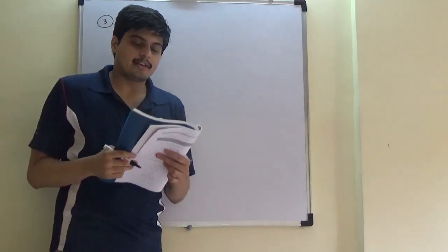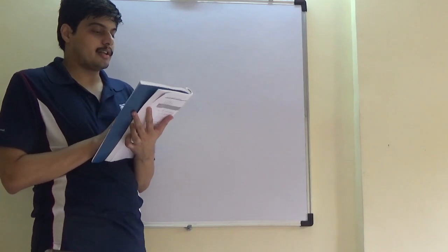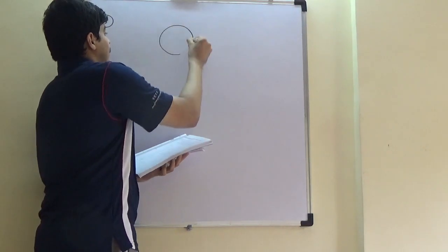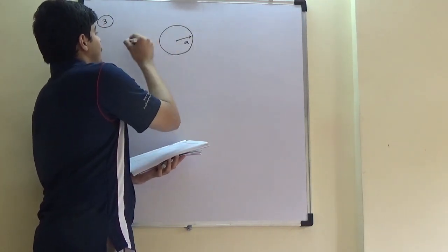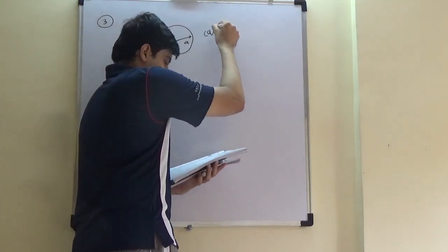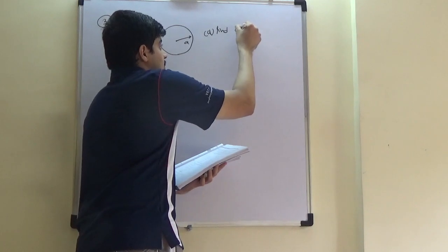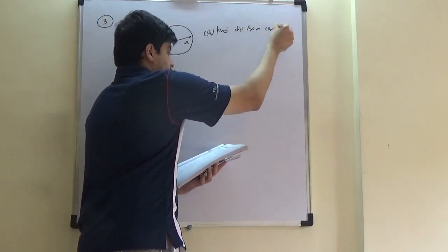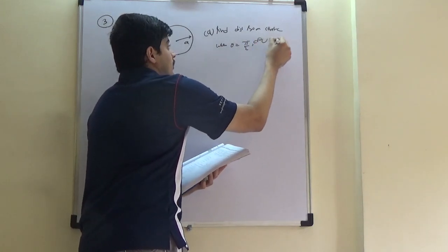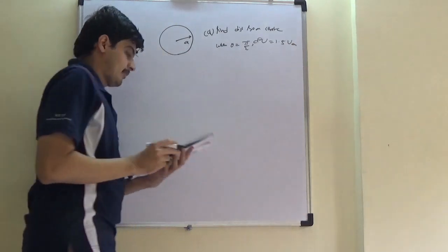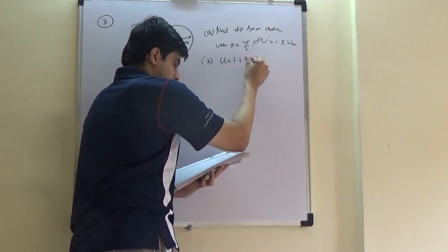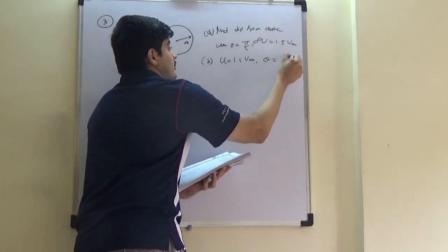On a stationary cylinder of radius a, there is a uniform velocity u infinity all over the cylinder. Stationary cylinder, radius a, u infinity. Standard problem. First, find the distance from the center when theta is pi by 2 and u is 1.5 u infinity. And second, u is 1.1 times u infinity, theta is 60 degrees.